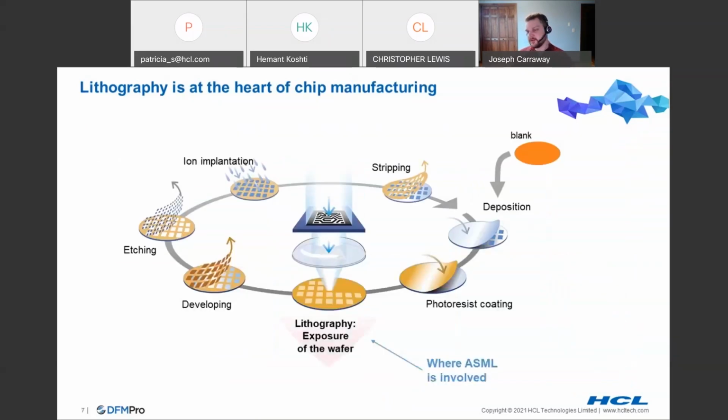And semiconductor in general, just so you have a frame of reference, people quite often see the silicon wafer with chips on it, but lithography is really at the center of this process. You start with a blank wafer, you deposit some material on it, you do a photoresist, and what we do is, if you think about black and white photography, you had a negative and you shine light through it. We focus the light. We call that negative a reticle, and we use ultraviolet light. And you put an image onto a wafer. It reacts with this photoresist, and there's a whole bunch of developing processes afterwards, but you end up with a physical structure on a chip, or that makes up a chip.